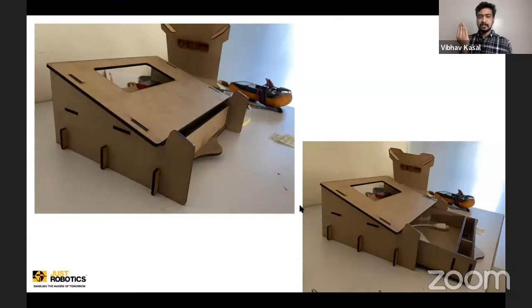You can give one test piece and ask them to cut this line at this speed, this line at this speed, and this line at this speed, and then examine how the cut has happened. Then you can decide, okay, use this speed of laser cutting for my entire design, laser cut it and give it to me.